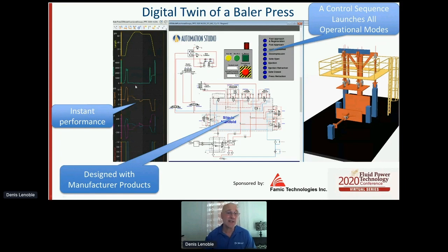We can recognize, of course, the hydraulics. So we have a pump group, we have a manifold with different pop-up valves, and we have external directional valves plus actuators. So this is a technical representation, an ISO technical representation, that can be used for design, can be used for technical publication, but that we also use to conduct FMEA.